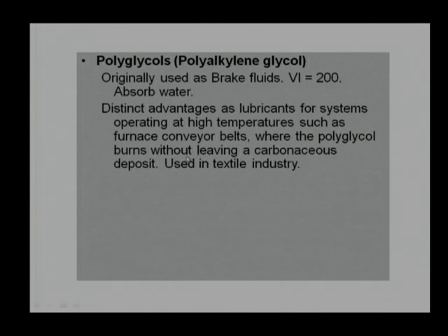And another thing is that they have good cooling capabilities, which is desirable. In addition, in a high temperature application, if they start burning, they do not leave any debris or any deposits. So, they are clean liquids, they vaporize, and they do not show that this kind of lubricant was ever there in that domain at all. So, they can be utilized in the textile industries where cleanliness is a prime requirement.